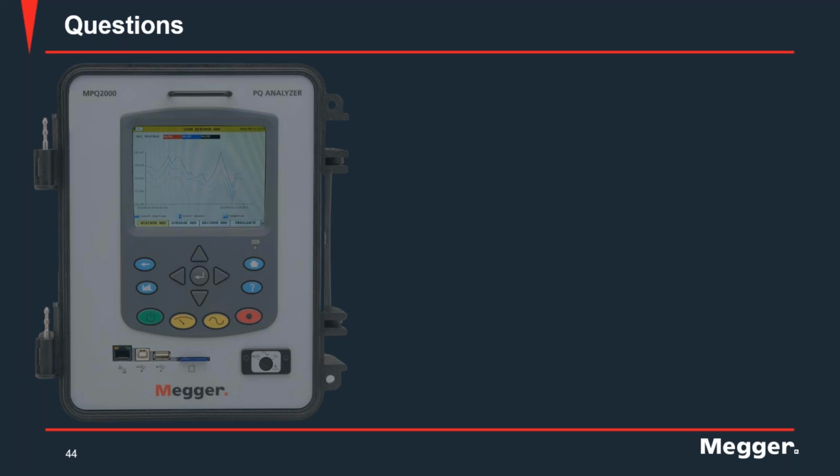Then if we move to the IEC world, there is a standard which Sanket also mentioned in his presentation. It's IEC 61000-4-30, and that tells you how your recorder should measure different power quality terms. And based upon that, you can define whether your instrument is a Class A or Class B type instrument. So that's IEC 61000-4-30.